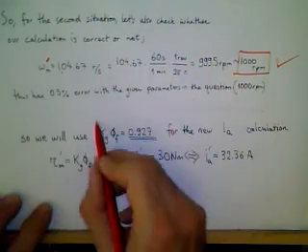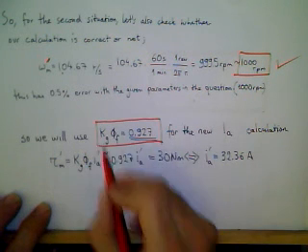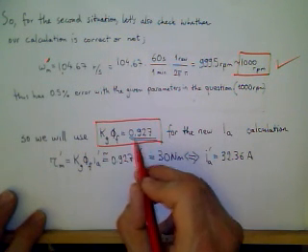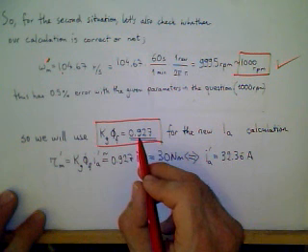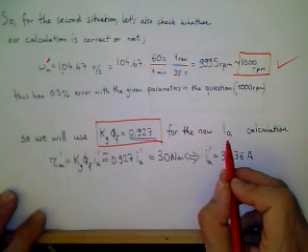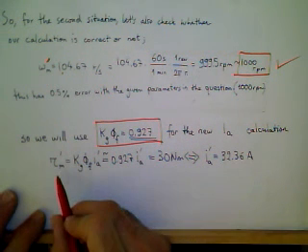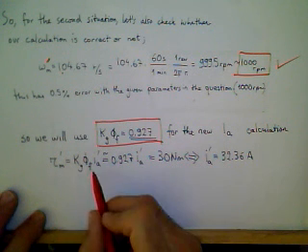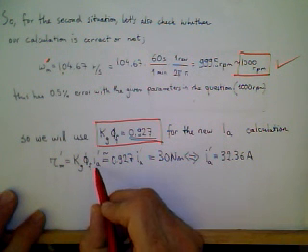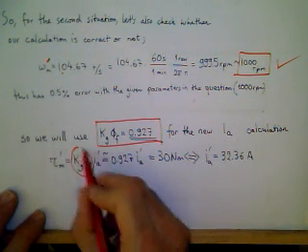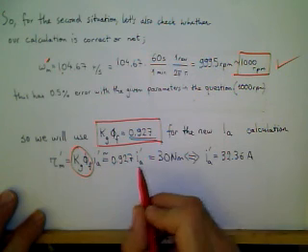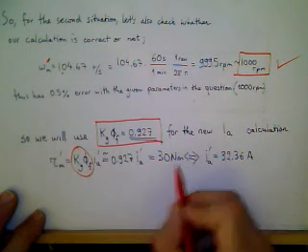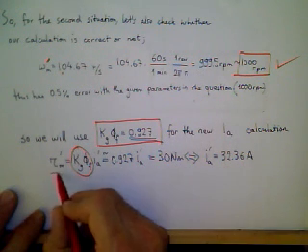So we will use that constant K times phi, the geometrical constant and field flux, of 0.927 for the new armature current calculation. The torque in the second case is directly proportional with the armature current, with the same constant. So we substitute this to calculate the new armature current, and torque in the second part.